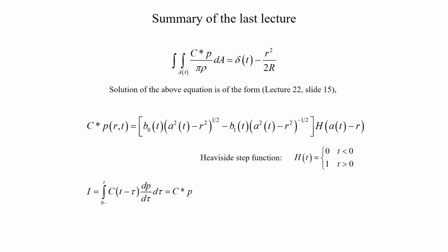In the last lecture we presented this definition of convolution, and then we also discussed that when there is contact on this elastic half space over this area A, because of this pressure distribution P, which is now a function of r and t.